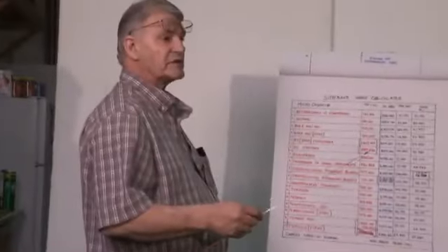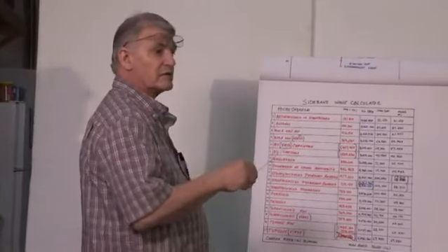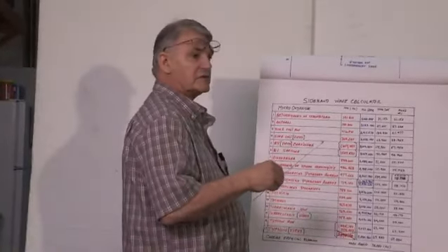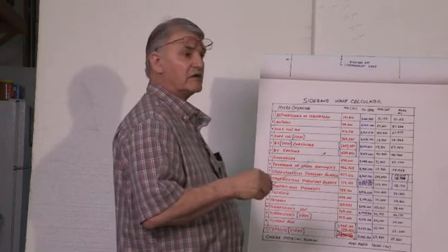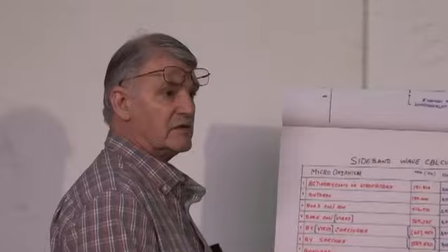Now, the thing about it is this work requires, I would really recommend the person doing this kind of work to have a spectrum analyzer. Or they're not going to be able to see. You're just second guessing. You're saying, yeah, we got the wave shape on the scope. The scope is not telling you what bands it's generating. So I think what we'll do is we'll cut away from here for a minute and we'll go back to the analyzer.